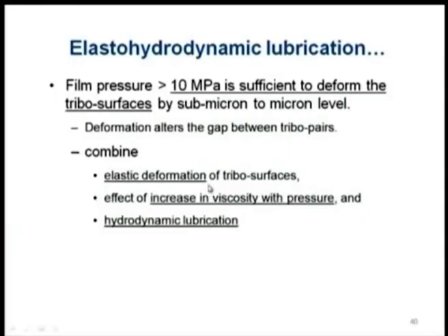And again, if the relative velocity is higher, the rolling contact is not happening for a longer duration, so the viscosity effect will not be dominating either. We are hypothetically thinking about 10%, but it may turn out to be maybe 2% or 3% depending on the relative velocity. So that may not happen substantially. That is why we differentiate elastohydrodynamic lubrication into soft EHL and hard EHL.